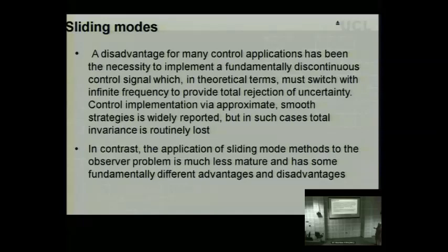They get the robustness of theory, but actually, for most engineering systems, there would have to be a compromise. You can't have switching. You don't particularly want switching with infinite frequency anyway, which is what theory says we need. And so we smooth, and because we smooth, we approximate.